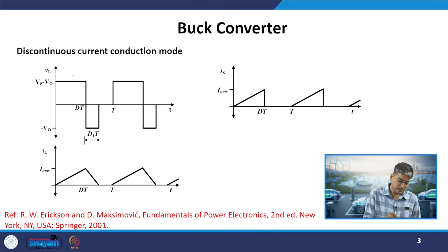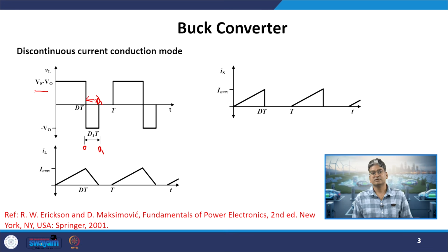If you see, when the switch was on, the voltage across the inductor is Vs minus Vo, that is the difference between input and output voltage. Now, till my inductor has energy, it will try to force the current through the output stage. So, this is the duration where we have assumed that the inductor is discharging completely at the D1 time instant. What will be the value of D1? Its measurement axis is shown from here. We are starting the 0 axis at the time when the switch was turned off, and it is completed when my inductor is completely discharged, or its flux is completely reset.